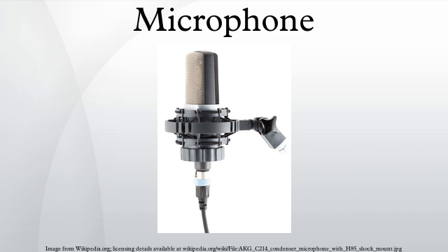Protective windscreens can reduce the danger of damaging a vintage ribbon, and also reduce plosive artifacts in the recording. Properly designed windscreens produce negligible treble attenuation. In common with other classes of dynamic microphone, ribbon microphones don't require phantom power. In fact, this voltage can damage some older ribbon microphones.